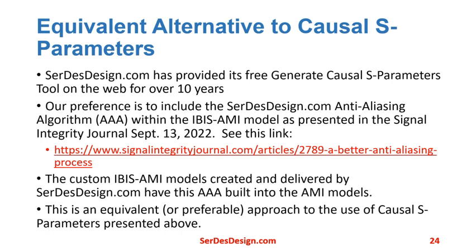The use of the AAA in the AMI models results in a faster channel simulation and relies on the AMI model to remove the channel impulse high-frequency aliasing along with no additional delay, while retaining the channel characteristics up to the original S-parameters maximum frequency.